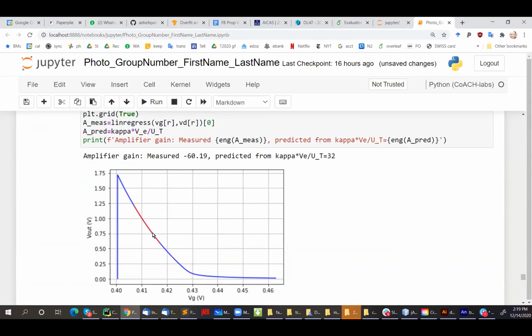Even though everything should be perfectly linear, this little bit of exponential here is making the gain different than what you predict from theory. And that is enough to explain the fact that it was ringing, because you assumed that you knew what the amplifier gain was from theory. And it wasn't that way, even in simulation. So that's the main reason that it didn't work out before.